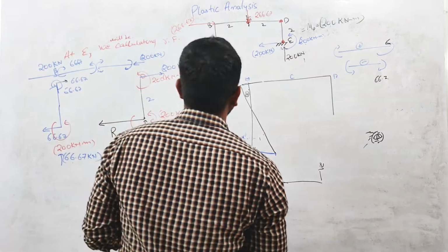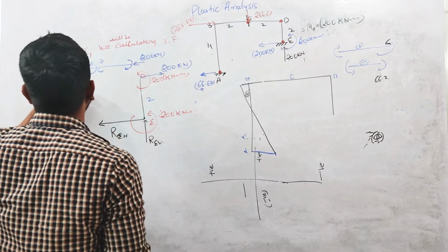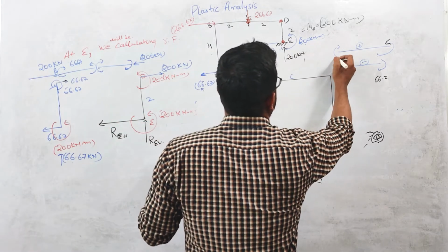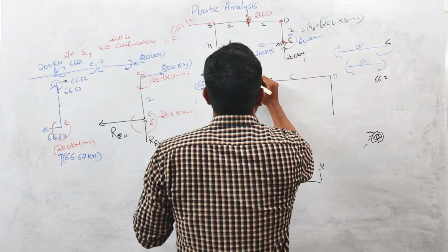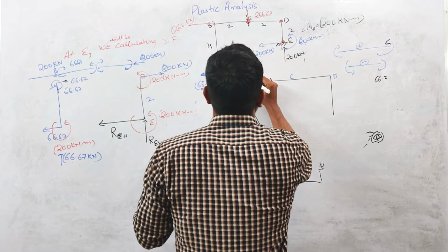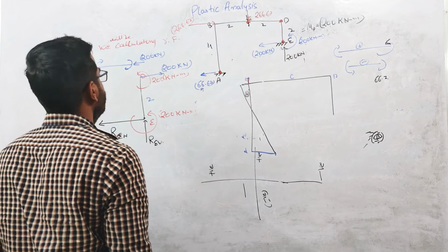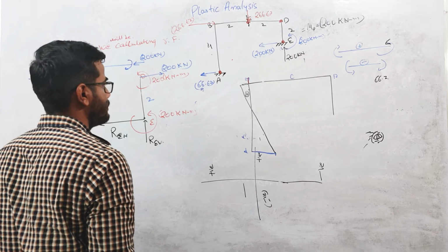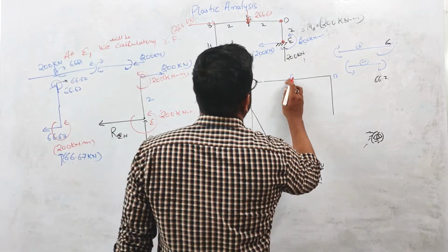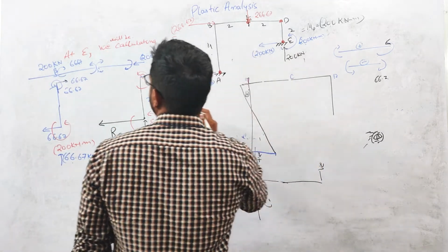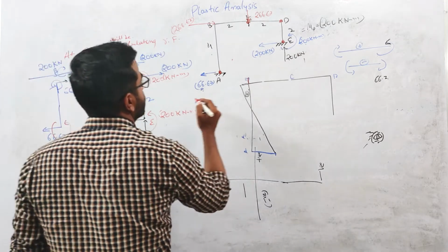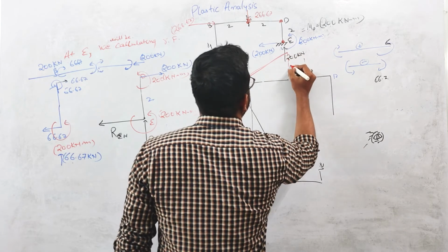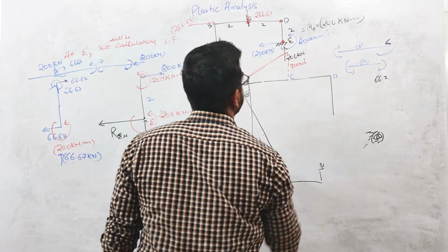Similarly, at this B point, for this member, you consider this direction. This clockwise direction is positive if we start from here. Okay. So again, it will start above this axis. Okay. And at C, the bending moment diagram, this direction will be considered positive, so it will move upward, and this magnitude will be 200 kilonewton, right?